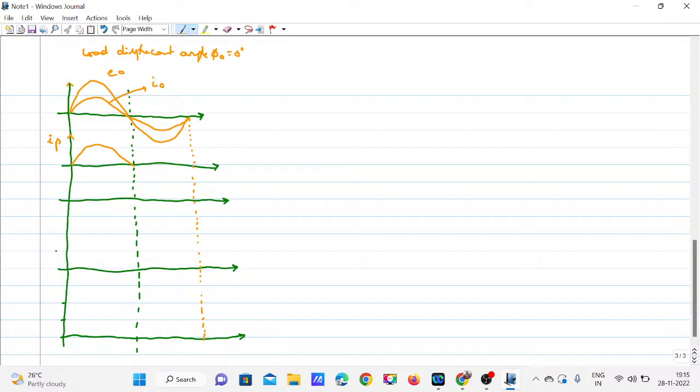So the diode will be reverse biased, so this current will be 0, like this. Okay, and coming to IN, if I want to draw IN here, in the positive half cycle its value is 0, and in the negative half cycle its value is full, like this. So by combining these two currents only, I have drawn that I naught, you can see here.